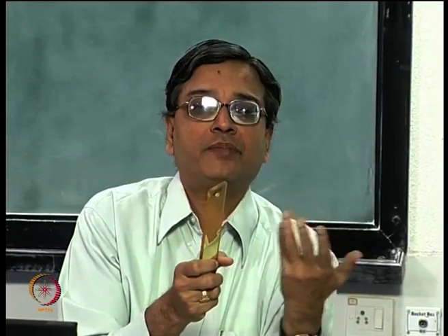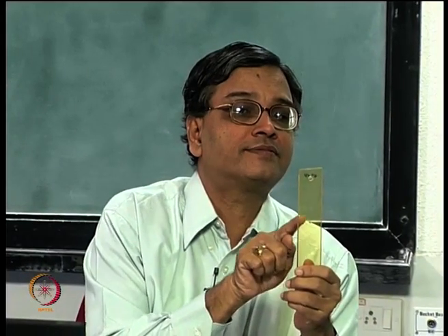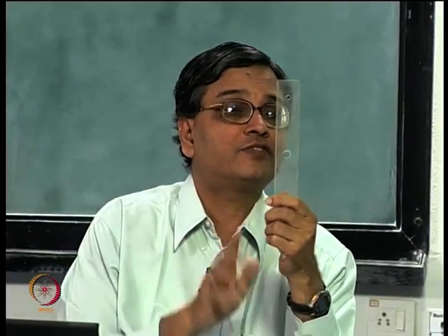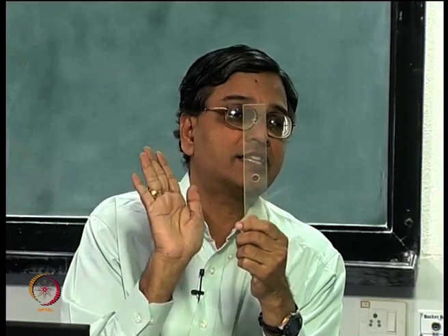You all learned in one of your design courses, when I have riveted joints, I have a series of holes. So, the idea here is, as an analytical method, you have been able to find out the presence of a hole, how it influences the stress field near the hole. You are able to get an analytical expression, and this will be a function of x and y. So, if you plug in x and y, you will be able to find the solution at every point in the domain, which is not the case when I take a finite geometry. This finite geometry is not possible to solve by theory of elasticity.